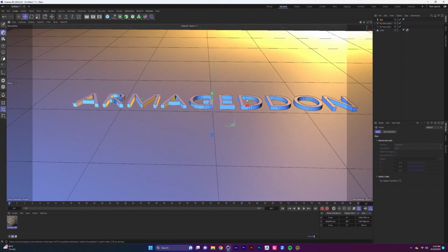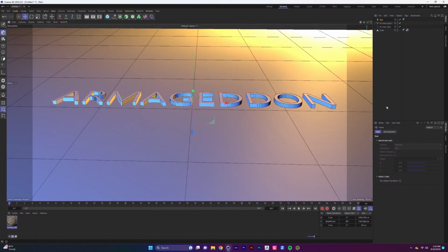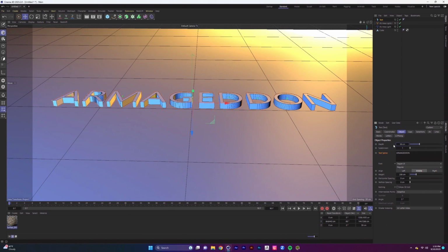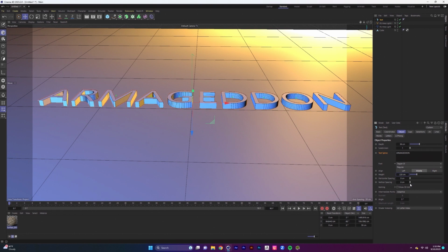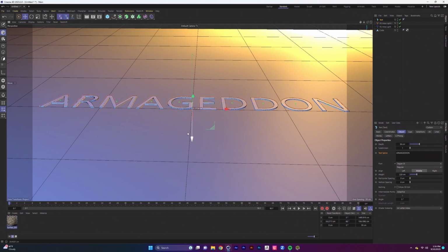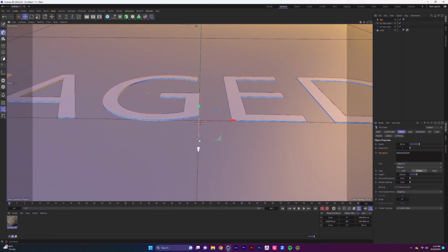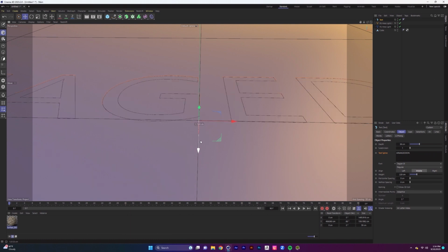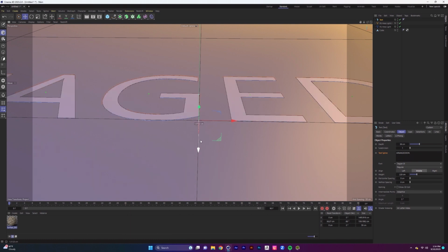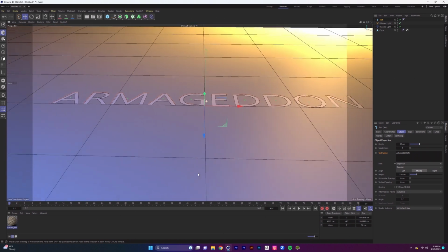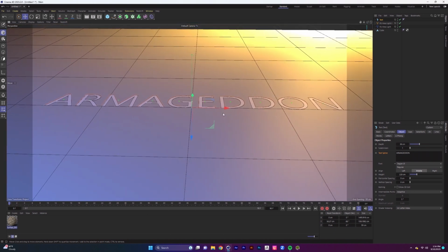All right, we're gonna scale it up a little bit. So select the text layer. Let's set the depth to 30. Subdivision is okay. Height, let's go to 20. And we'll set the text down into the stone, and we'll make sure that the top face of the text is just above the top face of our stone cube, because we are going to bool this.